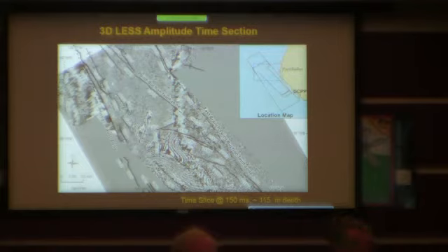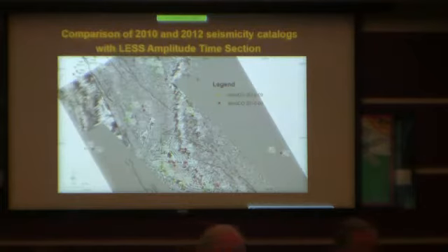So in our 2011 report to the NRC on the shoreline fault zone, we had identified a number of faults in the area in addition to the Hosgri. One featured in 2011 that we called the North 40 West Fault, using the new data that we collected in 10 and 11, we've now renamed as the Point Buchon Fault, and also come to realize and map in greater detail for this fault zone than we knew before. Next slide shows an overlay then of the seismicity, again these red and green dots that I showed you in an earlier slide, on this time slice. And again, to try to understand the correlation between geologic structure and seismicity in this area.